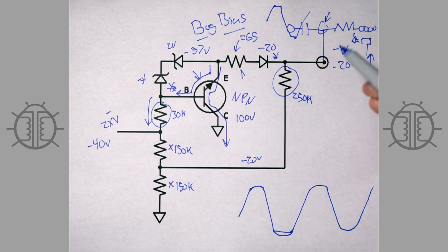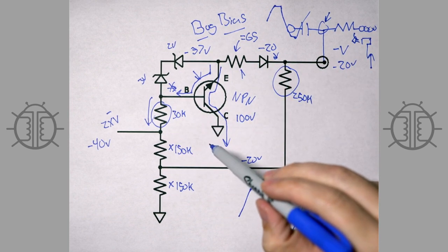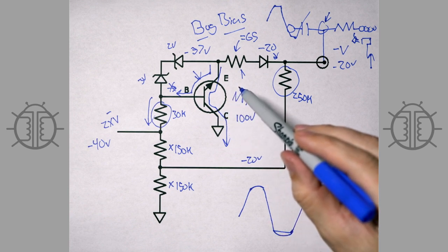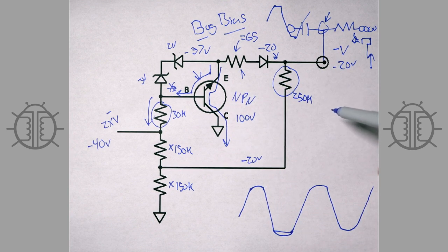I mean, you could take a bias board like this and put it into any capacitively coupled AB1 fixed bias stage, and if it suffered from blocking distortion that causes crossover distortion, this would eliminate it. Now, why do you want to do that, I guess, is a good question. The main reason is there's a time constant associated with the turning off of your output tubes. And when you clip, let's say on a kick drum or something like that, or a big bass note, your output tubes take a while to recover and return to their proper bias point. So that's not good if you ever clip your amp.